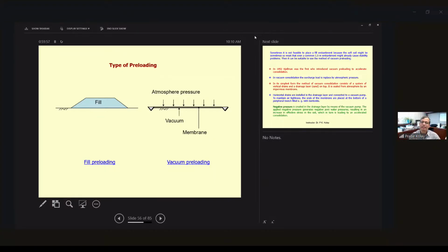Again, normally we cannot use the well point method when this is pure clay. If there is no choice, then you can use it. Sometimes you can also use the electrokinetic method, not only for dewatering. You can use that method for the removal of contaminants from clay soil also.